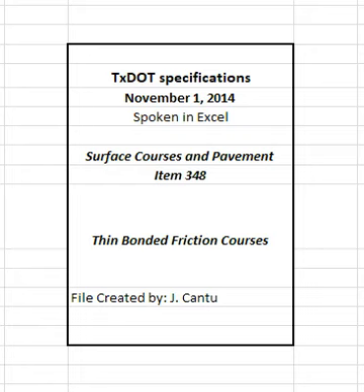4.4 Mixture design. 4.4.1 Design requirements. Use the design procedure provided in Tex-204-F, unless otherwise shown on the plans. Design the mixture to meet the requirements listed in Tables 7 and 8. Use a Superpave gyratory compactor, SGC, at 50 gyrations as the design number of gyrations.